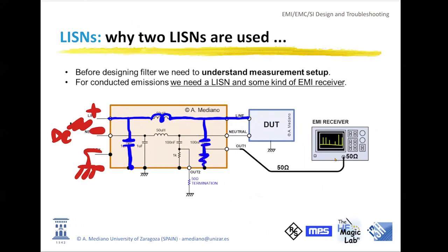Something like this. Usually the resistor that you see here, the 1K resistor here, in mains applications is used for safety. So the capacitors are discharged in this specific application, or can be used for damping resonances in the LC circuit.